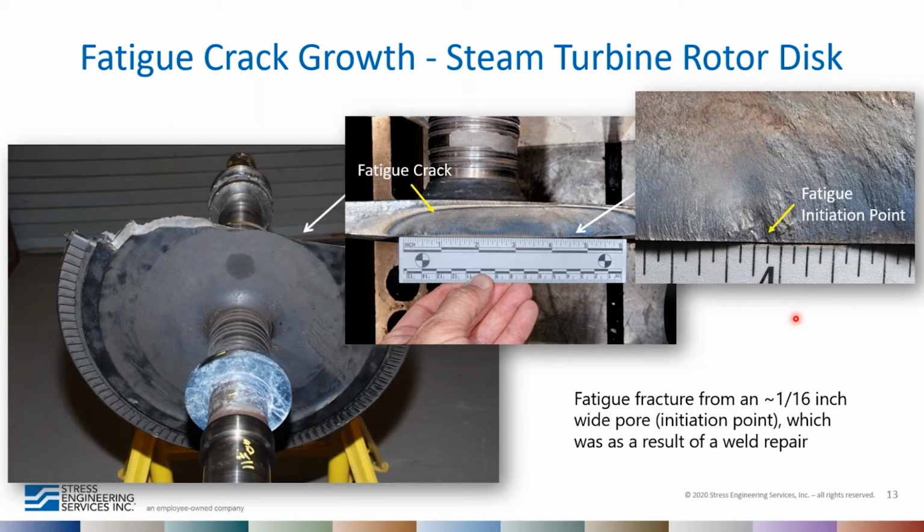And so really the pore was as a result of a weld repair, and further inspection showed additional such features on the surface. And so this was basically a miss as far as the inspection of these components in detecting these features before the component went into service.